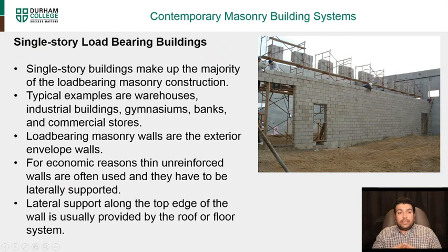Single-story load-bearing buildings make up a majority of load-bearing masonry construction. These are typically your warehouses, industrial buildings, gymnasiums, banks, and commercial stores. Small buildings, one story high. It's usually most economical and cost efficient to make unreinforced walls, and they have to be laterally supported.